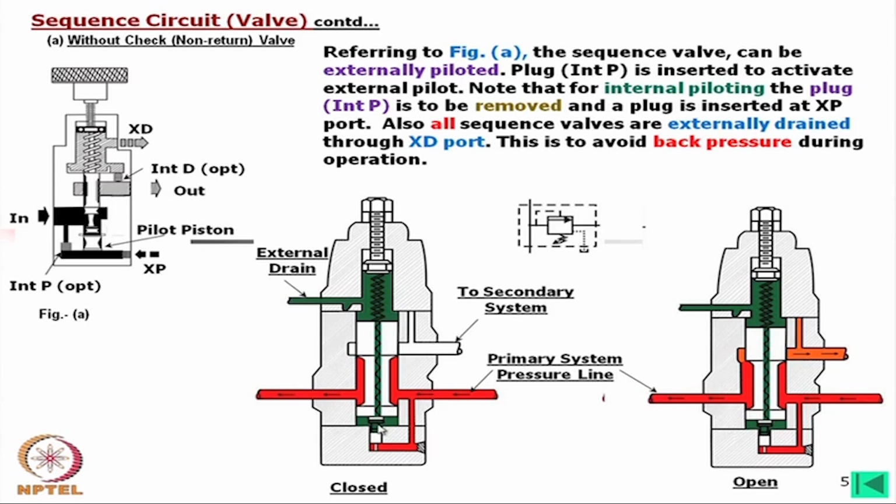Look into this, pressure is going through this, oil is going through this, it is coming over here. So, this side and this side is balanced, and oil pressure is here and here, this side is also balanced, unless there is a flow. Now, how will the flow begin?